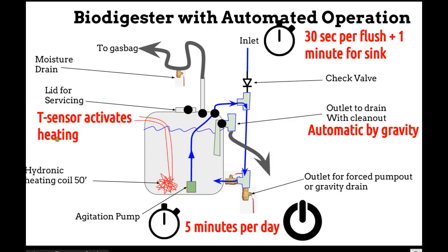With that, you also have a temperature sensor from the stove, so this biodigester is heated by the hydronic stove that we have. We would every so often take a temperature measurement, and run the heating into this if the temperature falls below a certain level. We want to keep this at about 96 Fahrenheit and up. So whenever we fall below our temperature, we pump heat from the hydronic stove. That's definitely available in the winter. In the summertime, hopefully it's warm enough. We're going to have to work out the interim days like spring and fall when we may not be having the stove running anymore and it's not hot enough to keep this warm, so we're going to have to work around that somehow.